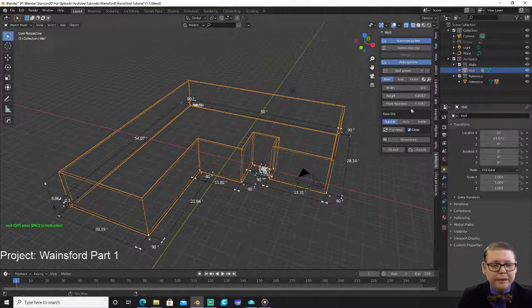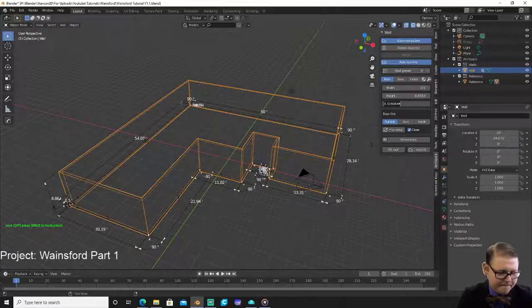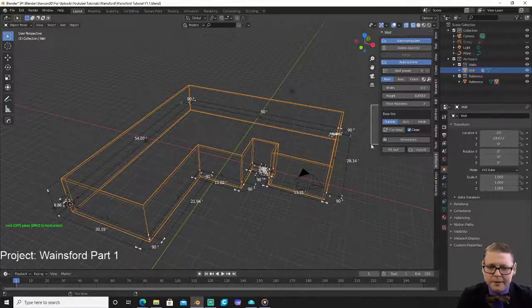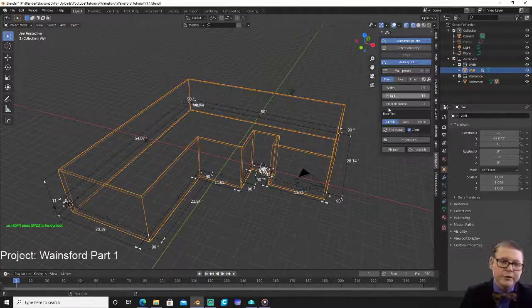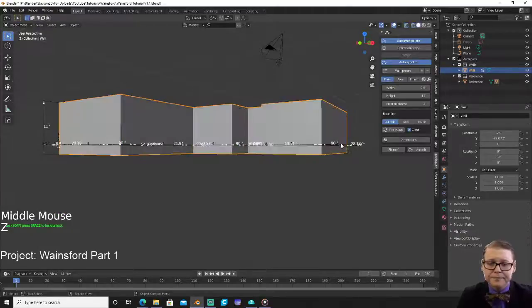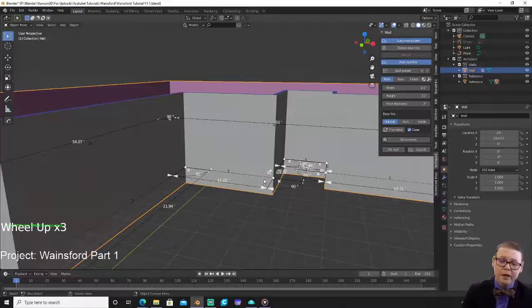Then what I'm actually going to do is make the floor 2 feet. And then if we go with a 9-foot wall, then the whole wall is going to have to be 11, 9 plus 2. And the reason that I'm doing that is it's going to drop basically what would be the foundation wall 2 feet below the ground.